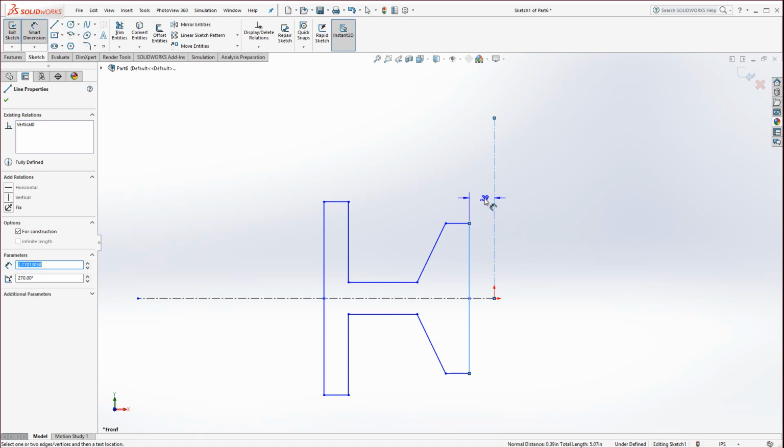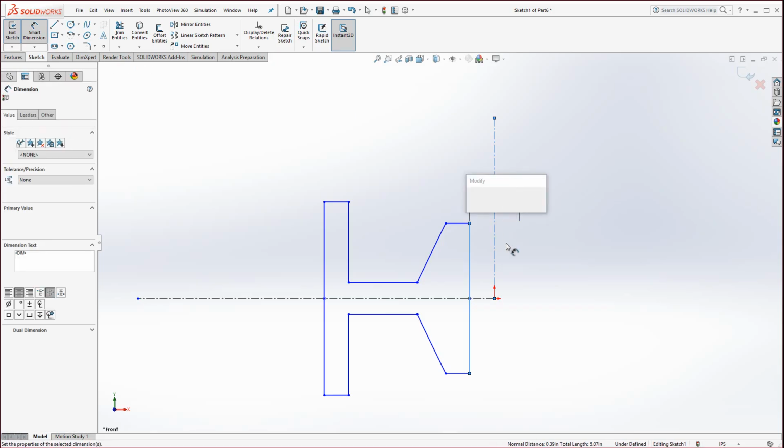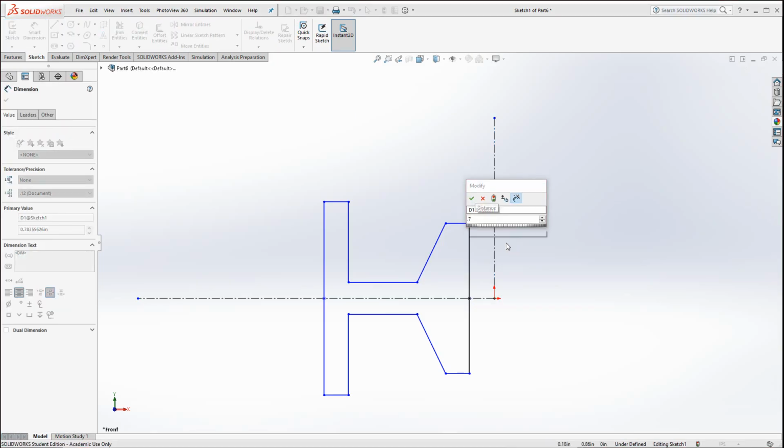Currently, if you're on the left-hand side with the pointer, you'll get just a dimension between the two. But don't click, just move the pointer to the right of the center line, and it gives you double that. It's essentially predefining what's to be a diameter, because this is going to be a Revolve. So it's a neat little trick, and it's nice because you could use these dimensions as diameter dimensions versus radius dimensions for your drawing later on. But let's go ahead and just click on the right side of the center line. Not actually on the center line, just where my pointer is. Click, and this needs to be 0.75 and hit enter.